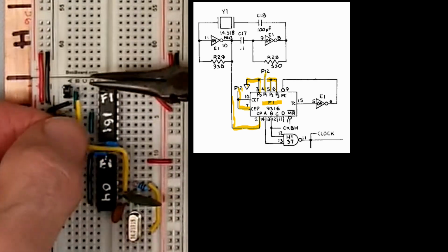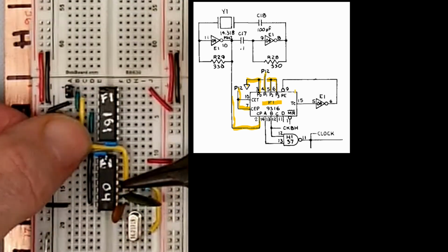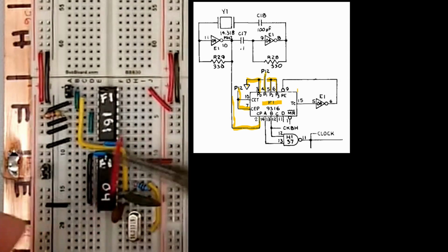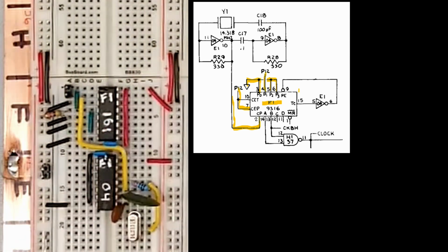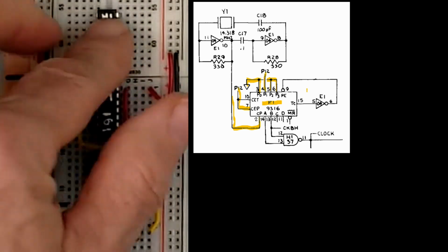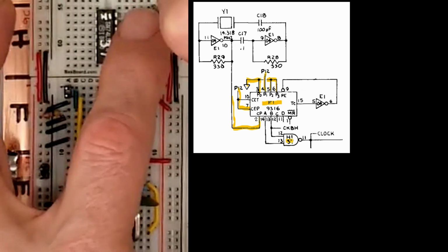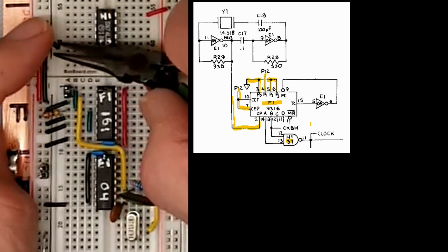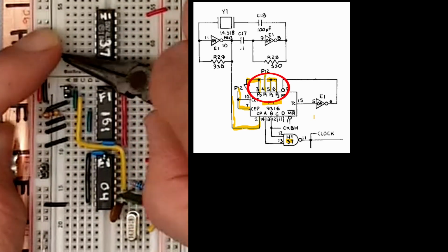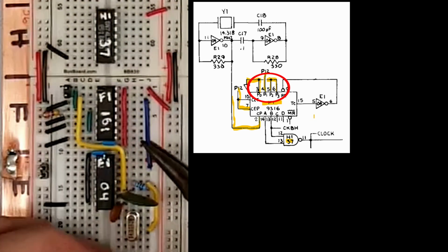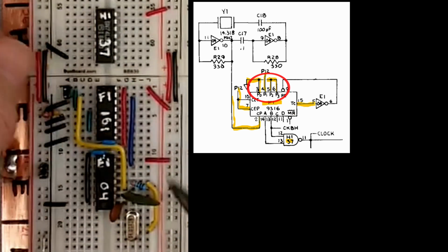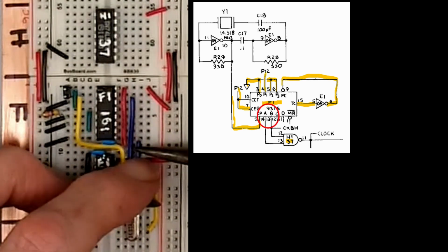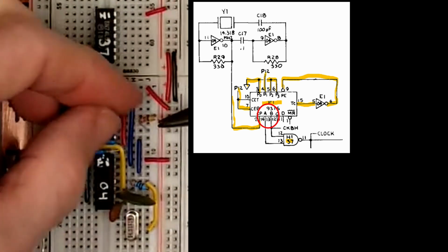For low-powered Schottky, outputs drive 10 loads, and inputs only consume half a load, so we should have plenty of room. Oscillators typically go through a buffer, but since it only goes to one input, there's no need here. This counter is configured to reload to 2 after hitting 15, so basically it's an offset modulo 14 counter. The system clock is then derived by ANDing the first 2 counter output stages.